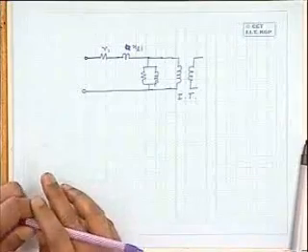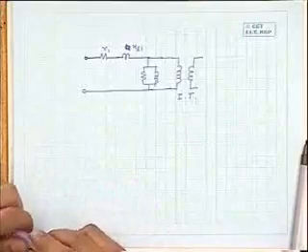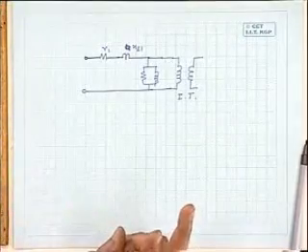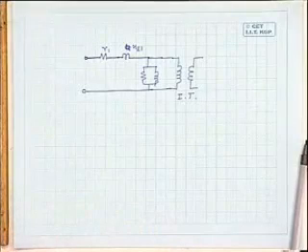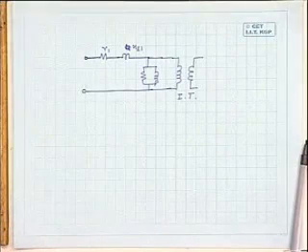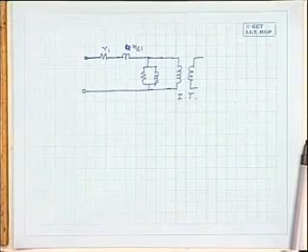So to conclude today's lecture, I have discussed today one of the important things, that is the core losses in a transformer. Core losses in a transformer comprise hysteresis and eddy current loss. Both of them depend upon the level of flux density, that is Bmax, and the supply frequency. In a transformer particularly, we know that the flux density level does not change substantially from no load to full load. Why am I using the word substantially? Because in a practical transformer, we will see that it may change slightly, but not to be taken note of very seriously. We can make a general comment that core loss practically remains constant.